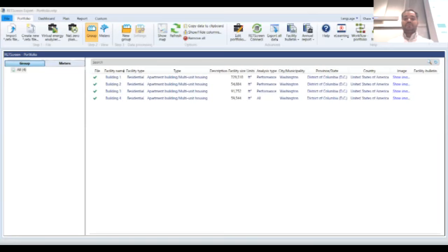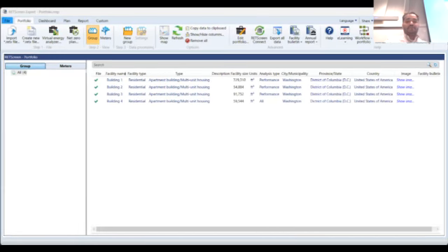The way it is done, for people who already have Energy Star Portfolio Manager access, you go into the account settings, software development, and you need to enable your web API services, and just mark it as yes out here. Once you mark it as yes, Energy Star will take approximately a couple of days to approve API access.